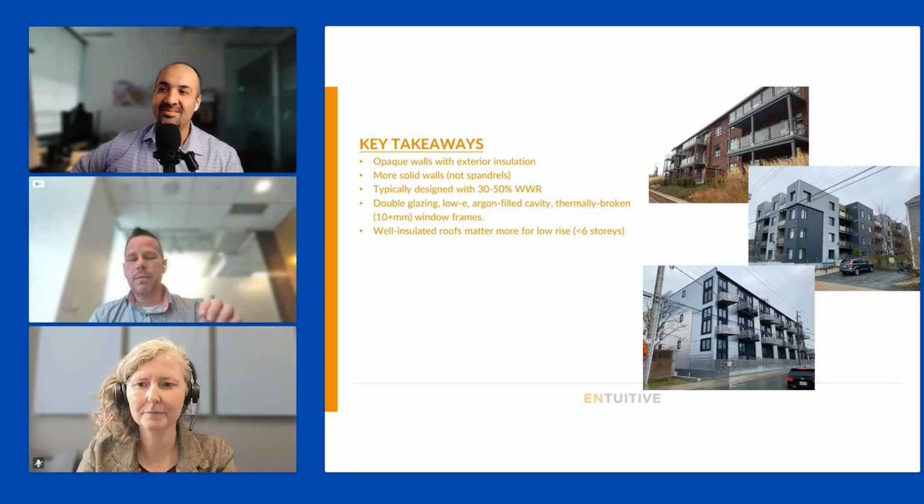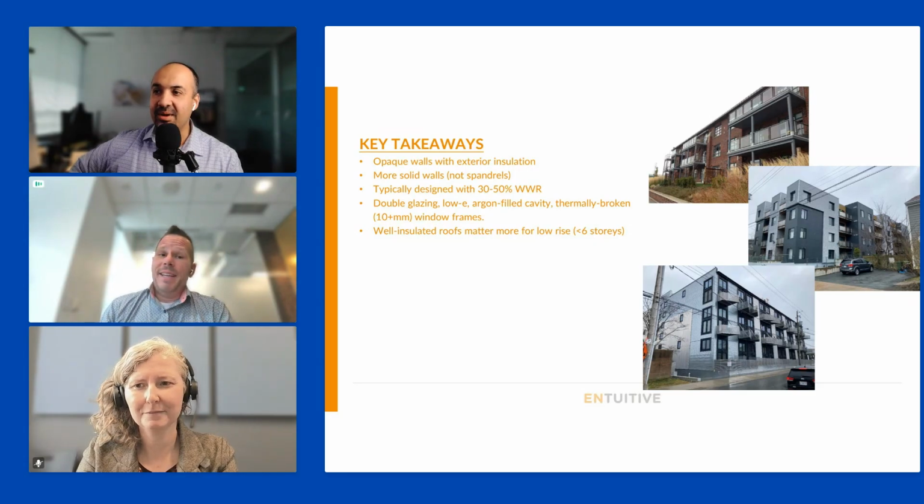So that kind of integrative thinking, and then I'll just show that top photo is a good example of these decoupled balconies. These are separately supported, or at least not fully cantilevered balconies, separate from the enclosure, and then connected in a thermally smart way, just with a pin connection at the wall. So just maybe a lateral or something a little bit lighter there. But nothing like our traditional cast in place with the window wall sitting on top of it. It's tough to do that these days. The other thing I would say is the prefabricated bolt-on balconies are also an interesting strategy. Expensive, but good.